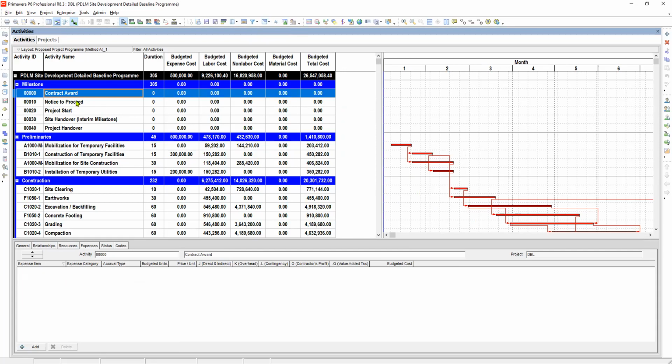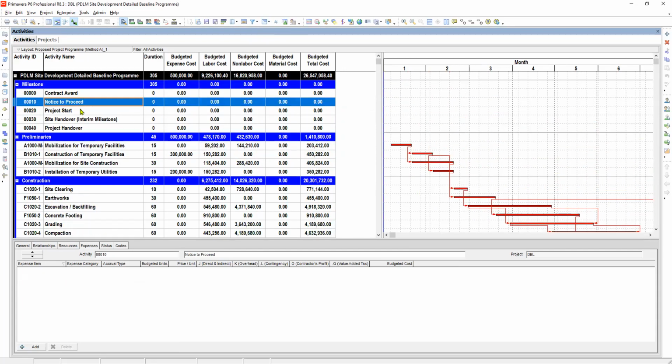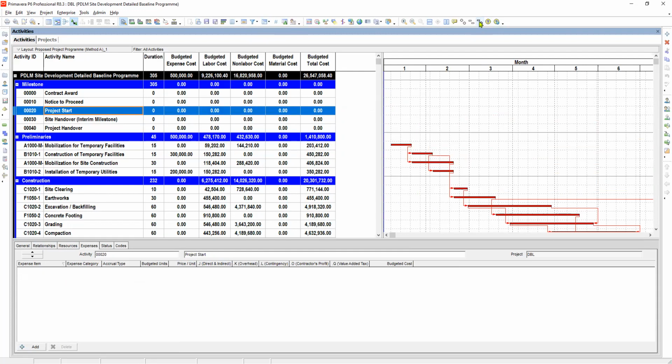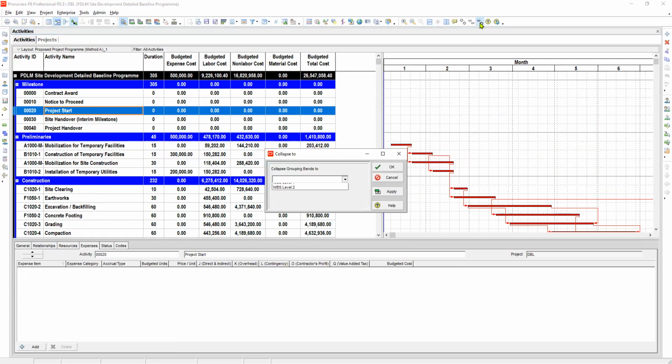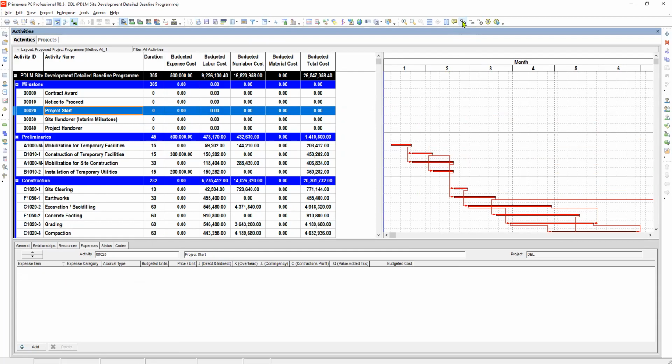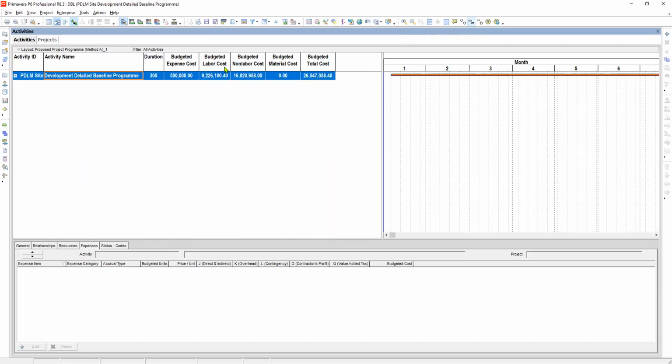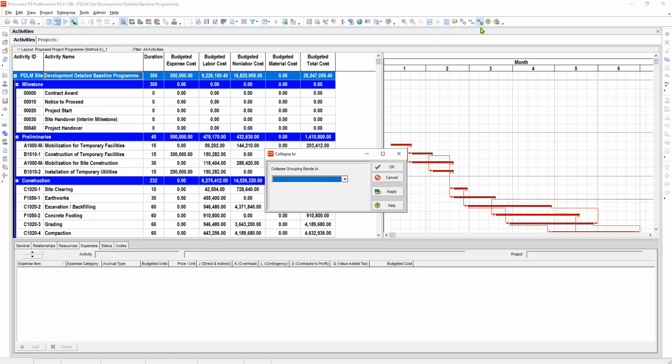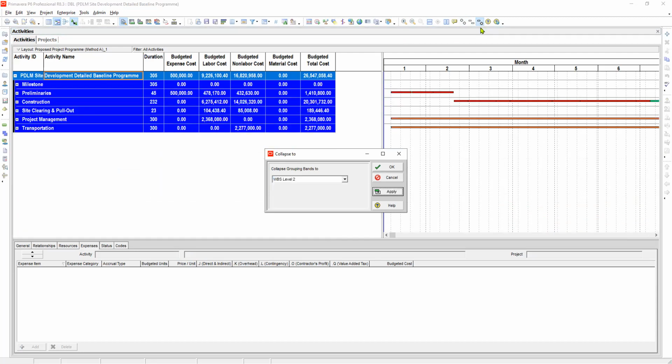Okay. Our WBS is here. It's so very detailed, so we will change the label using this one. Have you seen this one? If you click this one, it will spread out every activity. If you click this one, it will collapse into a project label. If you click this one, it will collapse into an activity label. If you click this one, you can select a label that you want to show or display. So we will look, let's say 2, and then apply.